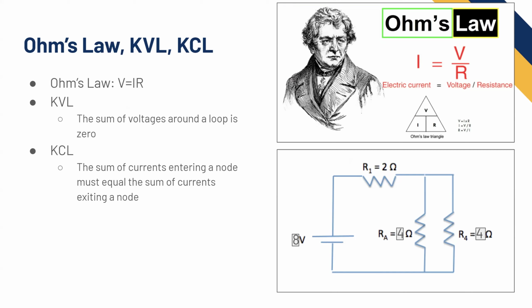Now, there are two ways to find the voltage. We know the current: it's 2 amps coming out of the voltage source. Now we want to know the voltage on the top right corner. There are two ways we could do that. We could take the current that we just figured out, and however much current times the top resistance will drop from our 8-volt source.